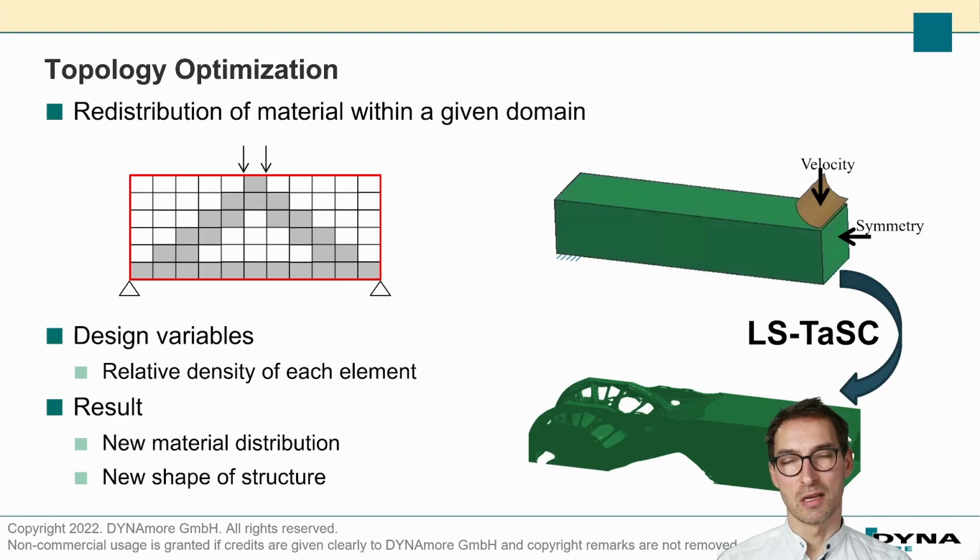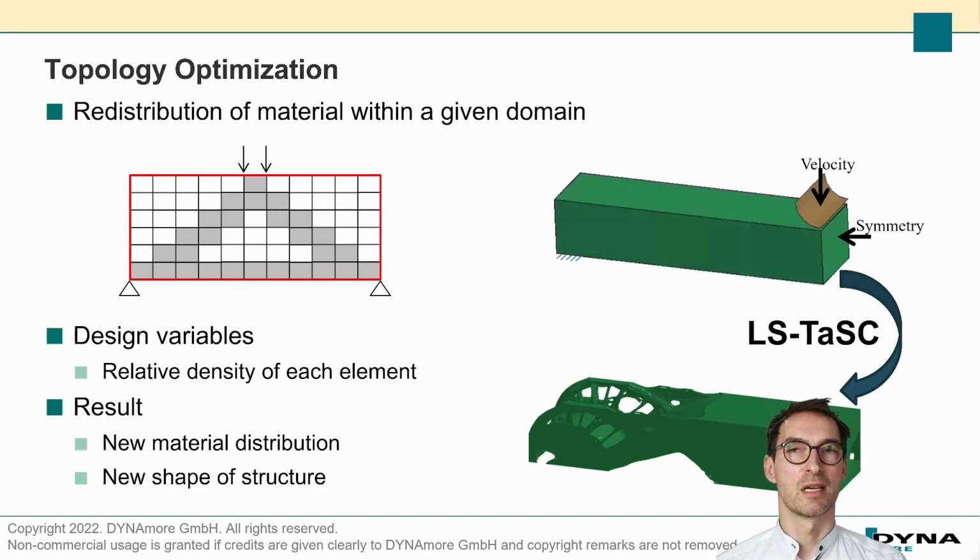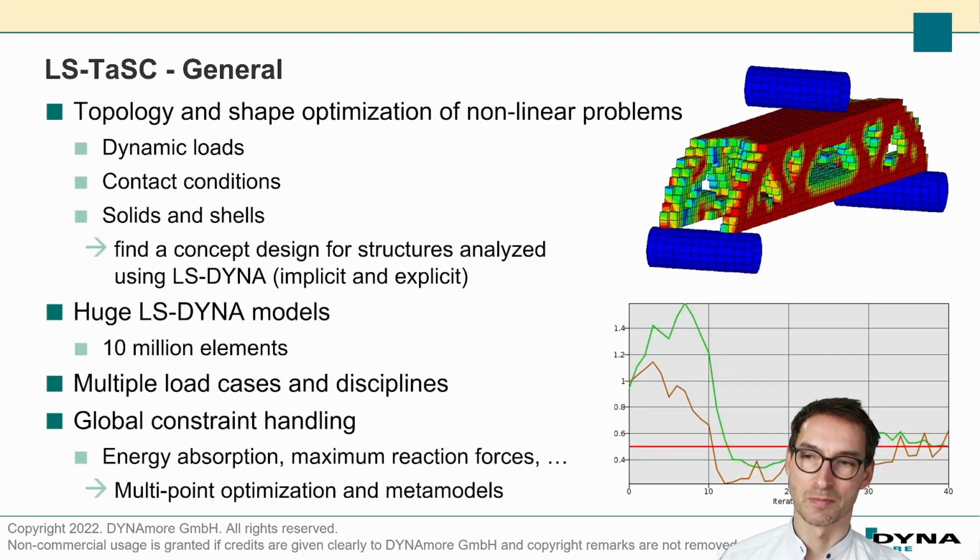Yeah, and then you can export this design and start working, redefine it using CAD geometry, and then, I don't know, take a look at it production-wise. Can I produce it like this or not? But this is a really good approach. If you have a new part you need to create, you have these load cases, and LS-TaSC may give you at least an idea how the design has to look like. So it's a very good approach if you have a new part in your portfolio.